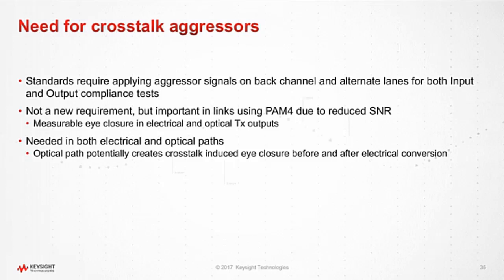I've actually seen it. I wanted to put it in the slide. I apologize for that. The material I saw was copyrighted. I was not able to get copyright permission to duplicate it. But I actually saw an example with a real optical module where we were making the measurements that Rob talked about. They were measuring the optical output measurements from the PAM4 signal, and when they put a received optical signal back into the module in the receive path, that actually closed the eye, a good amount of eye closure. So it's very important that you do it.